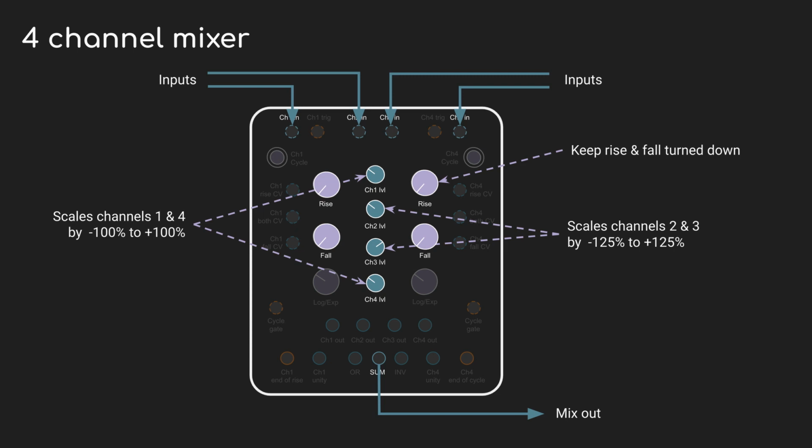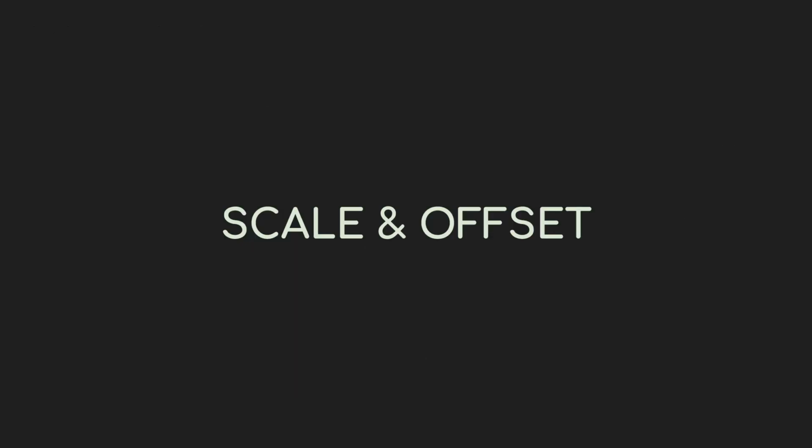Each of those channels can take an input, either CV or audio, and mix them together and send them to the sum output. If you're cycling channels 1 or 4, that'll also be added. The only real limitation is that sum will only output in the range from -10 to +10. So if you were to set channels 2 and 3 fully clockwise, that would be 10 + 5 = 15 volts. But to keep our precious modules safe, Make Noise maxes out at 10 volts, and everything after that is ignored.